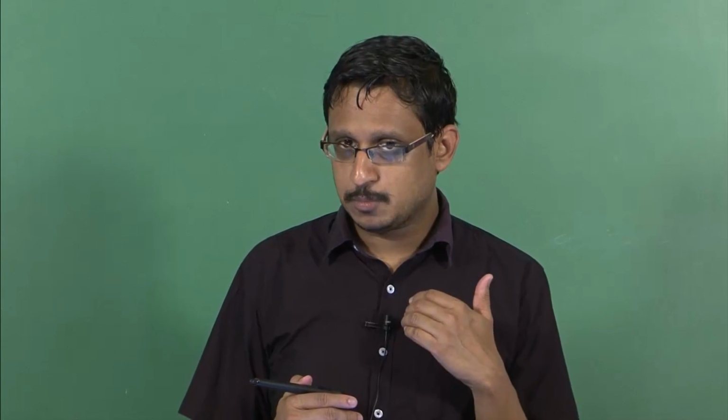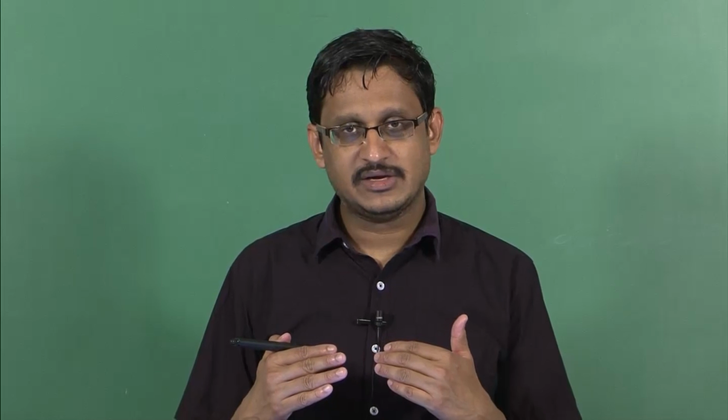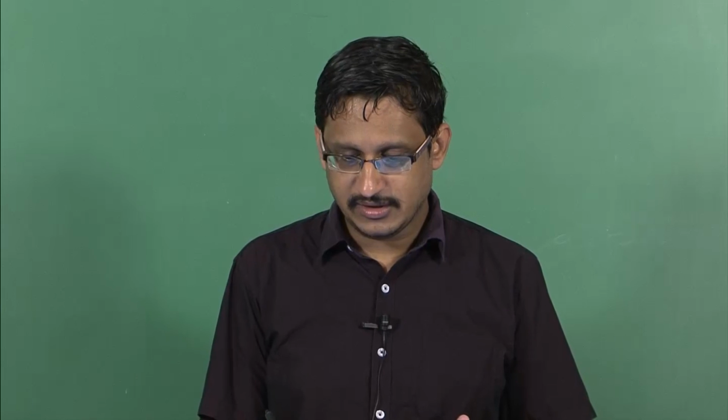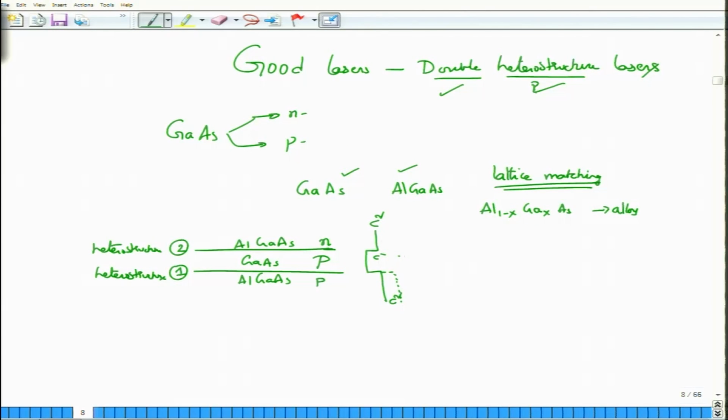Because one of them is P doped, the other one is N doped, the refractive indexes are not exactly quite the same, but most importantly, even if this is not exactly the same, it is important to note that the central region has a larger refractive index. What is the implication of having a larger refractive index? Well, the implication of this central region having a larger refractive index is very obvious, that you can actually put a mode into it. This corresponds to a nice slab waveguide and therefore can support an optical mode which would then propagate along this active layer.